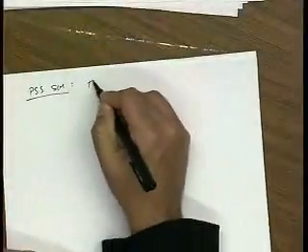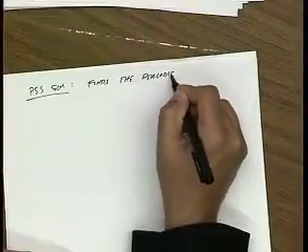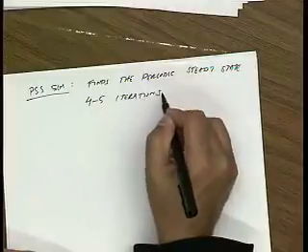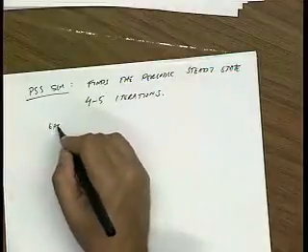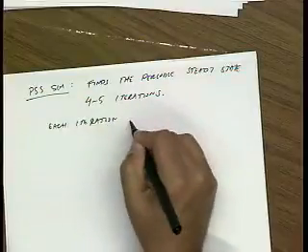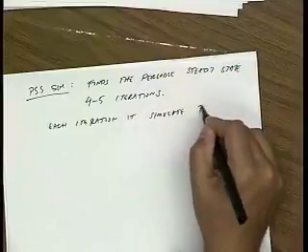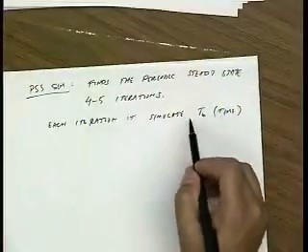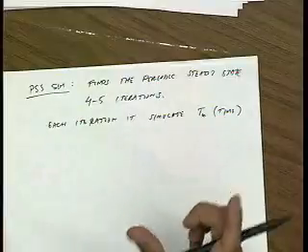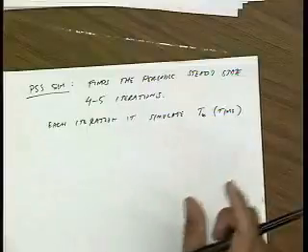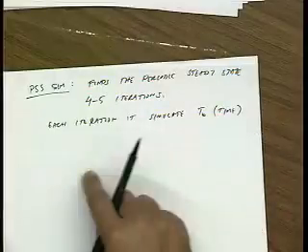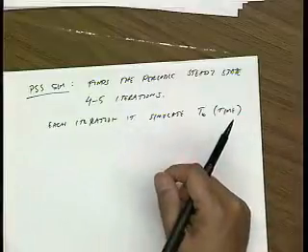So a PSS simulation finds the periodic steady state in usually about 4 to 5 iterations. And the way it does this is, in each iteration, it simulates about T naught, basically. So it only simulates roughly one cycle of the circuit. So within 4 or 5 iterations of simulating one cycle, it finds the periodic steady state. Now that's really powerful, right? So if we could use this information, we only need to do about 4 or 5 iterations, 4 or 5 periods, as opposed to, like, let's say 10,000 periods that we talked about before.